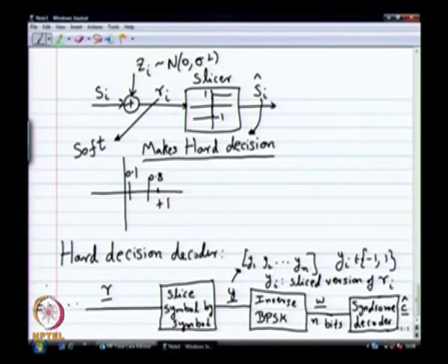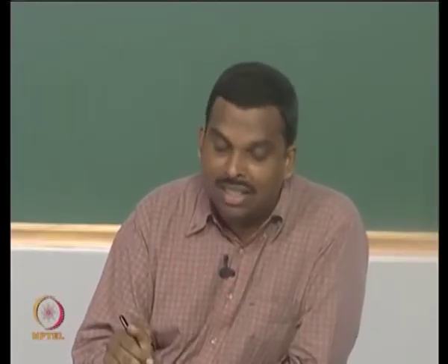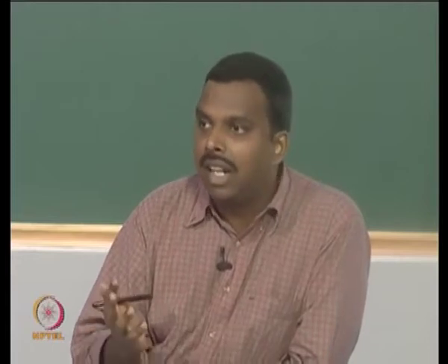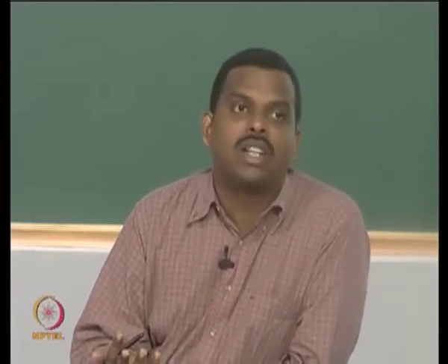So, from the code word to W, I have a binary symmetric channel. So, clearly the syndrome decoder is an optimal ML decoder, you get it. Okay, so, this is the hard decision decoder, and this is the same picture like we had before. You are really not doing coded modulation here. It sounds like I am doing coded modulation, but the slicing symbol by symbol is basically an independent demodulation. I am not taking the coding into account when I do slicing symbol by symbol.